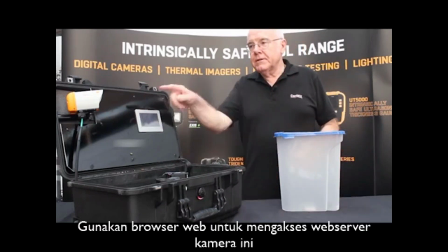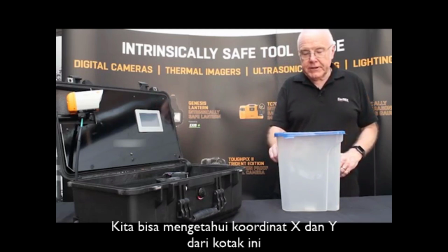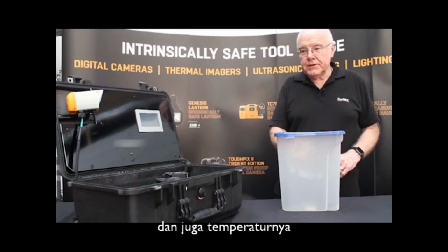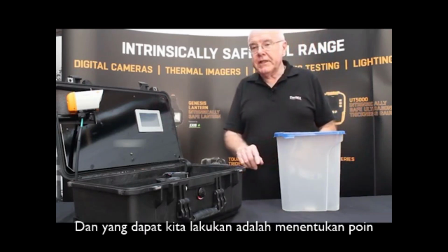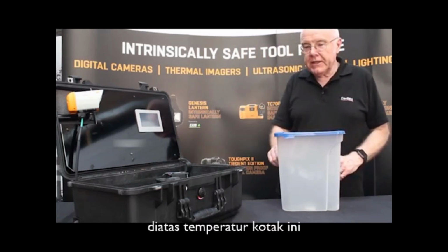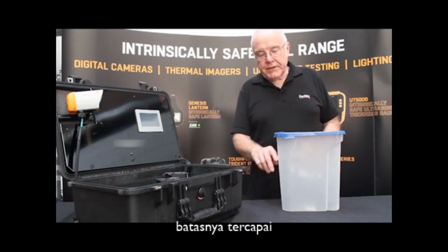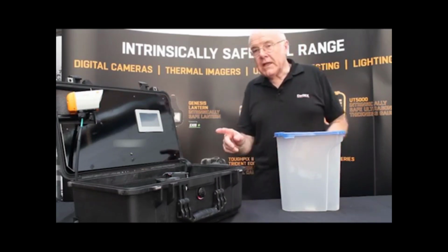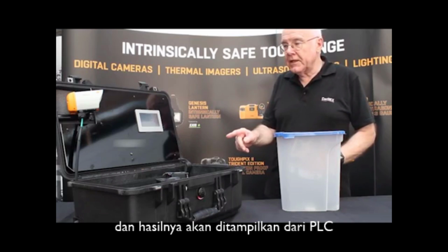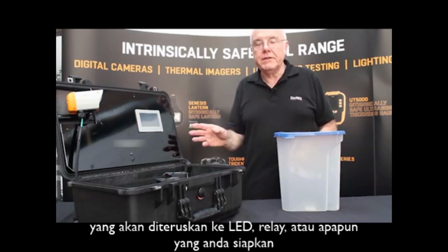Using a web browser to talk to our web server in the camera, we can ascertain the X and Y coordinates of this container and also the temperature. And then what we can do is set a set point above the temperature of the container, and as the liquid is poured in, the threshold is reached, and then an output will be given out from the PLC, which will go off to an LED or a relay or whatever you would like it to do.